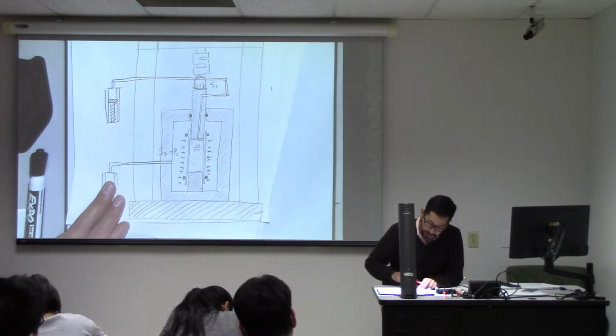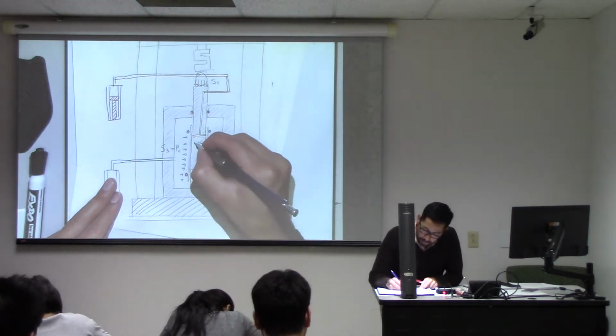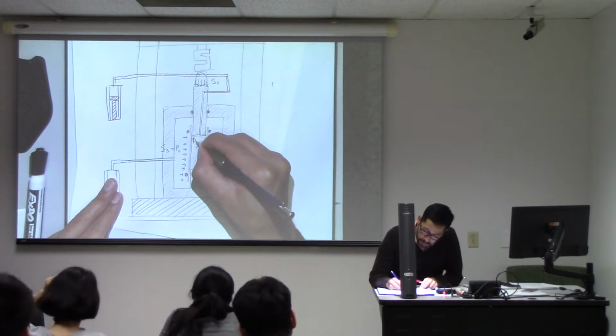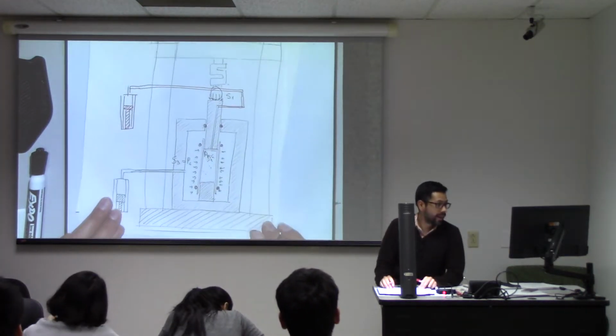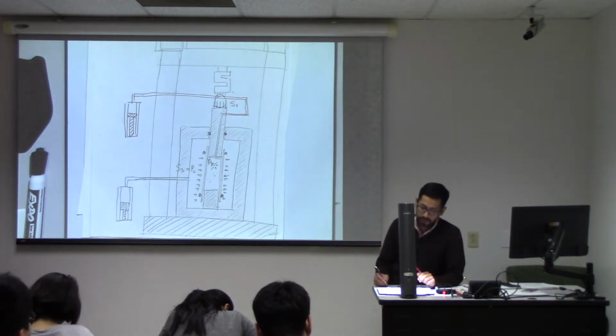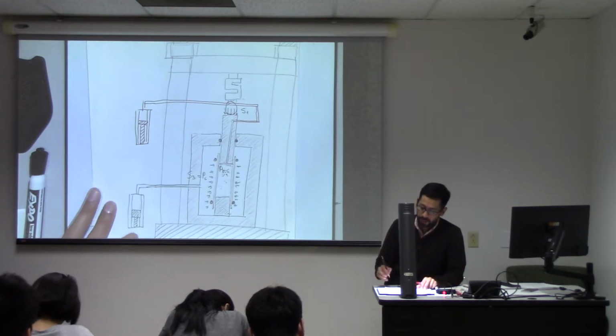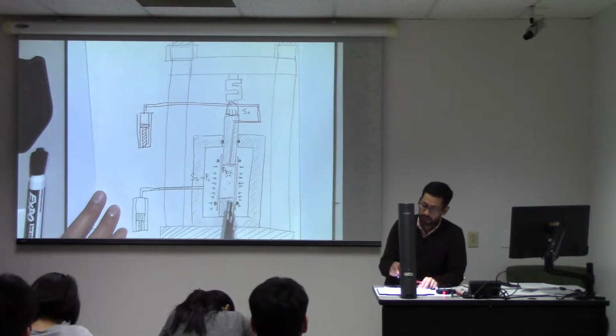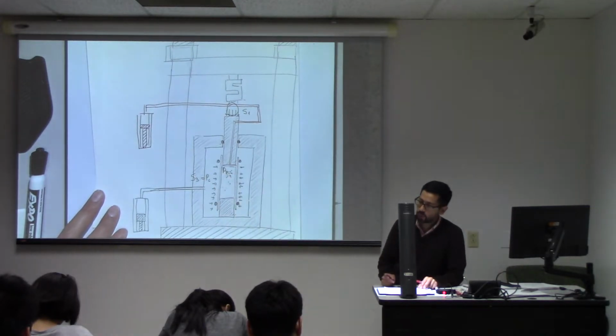And remember that inside here, let me write a little bit bigger because it's too small, you're going to have the pore pressure. And the test consists in keeping confining pressure constant, pore pressure constant, and increasing S1.